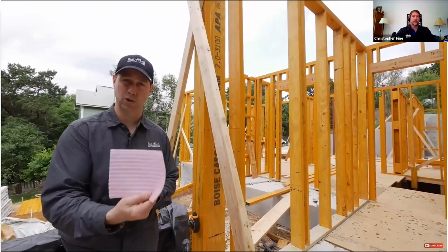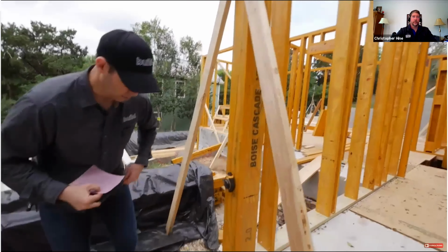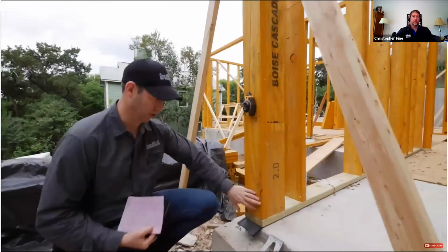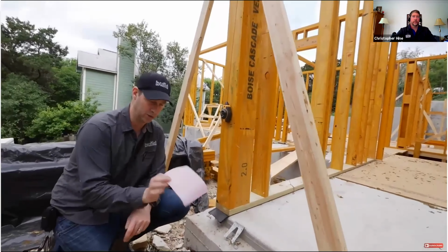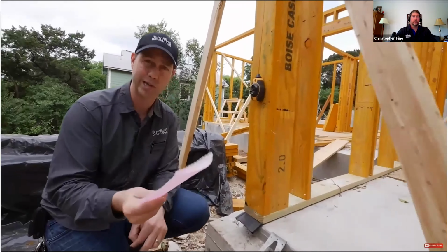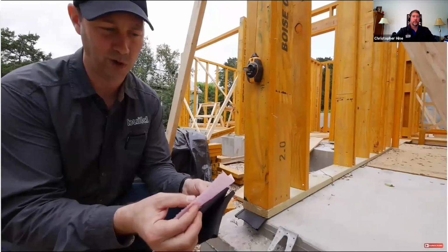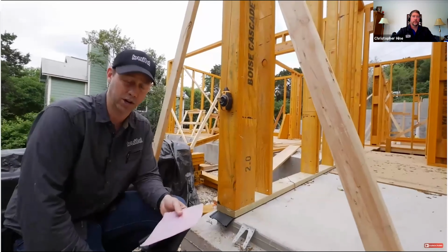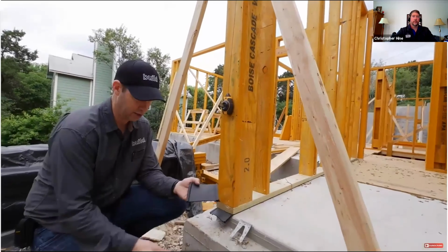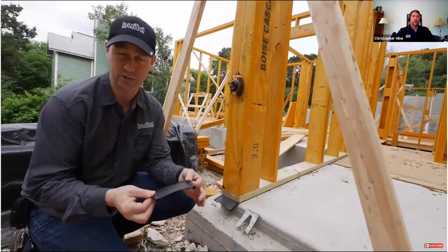This is what most builders across the country are using for air sealing at this connection between the foundation and the framing. So here's our 2x6 bottom plate right here. This is what's commonly used. This does a good job of a capillary break and it provides some air seal. But if you look, that real thin foam is not doing a great job if we've got any undulation in our concrete.